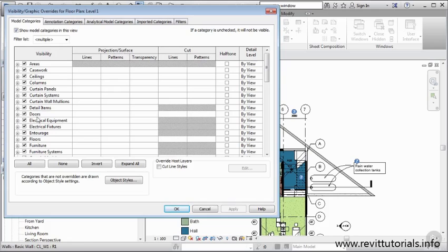Now, just above this main area here, we skipped over this just a minute ago, but I'll come back to this. We have the ability to filter this list. One thing we know about Revit from our discussion is that it's a tool that allows all the main design disciplines in AEC to work on the same model. So you're going to see elements inside your model that apply to architecture, structure, mechanical, electrical, and piping. Luckily, we're able to filter this out. In this particular project, or this template that we're working in, we basically can only see the architecture and the structure elements. But if you wanted to see more, we can definitely see more by simply checking.